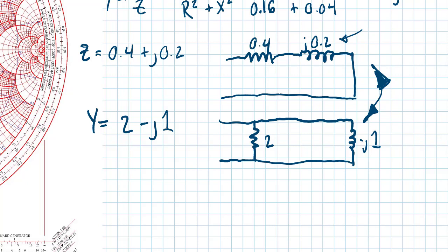So that implies if you are developing a circuit and your calculations achieve some component values that are unrealistic, for example, if you had a series circuit, you could see whether the equivalent parallel circuit gave you some more realistic component values and substitute that in, as long as you only needed the performance to work around one particular frequency.